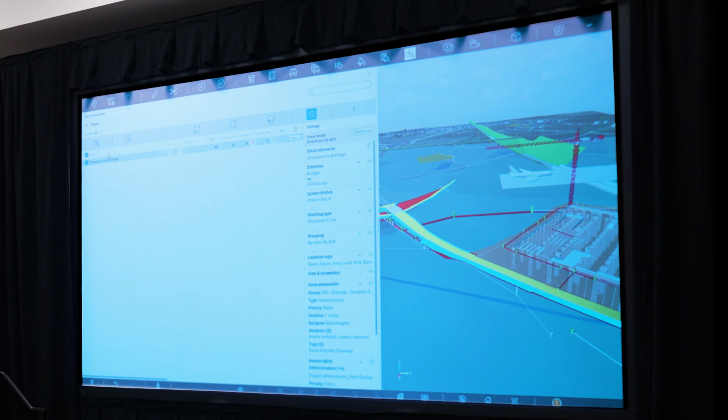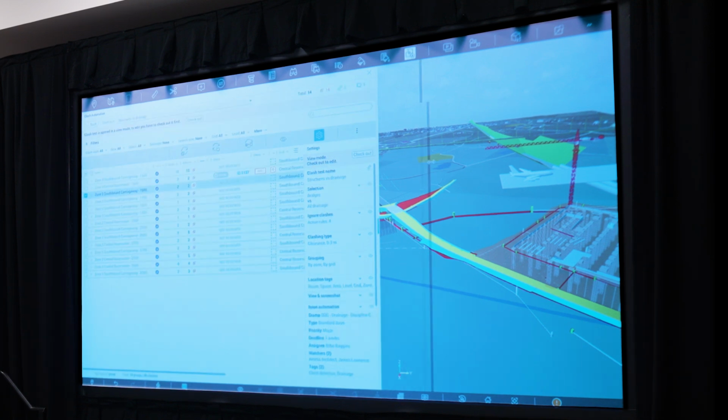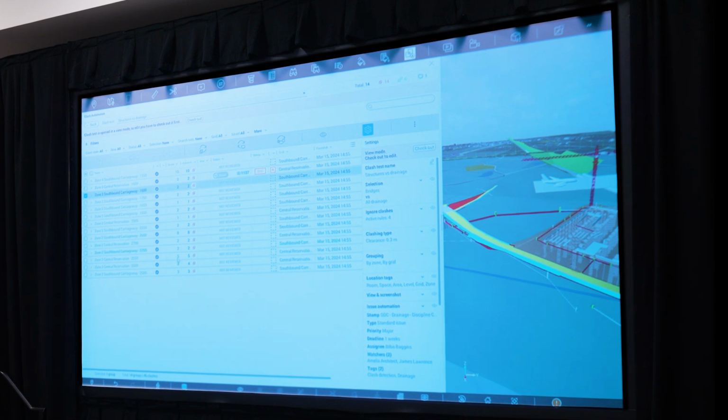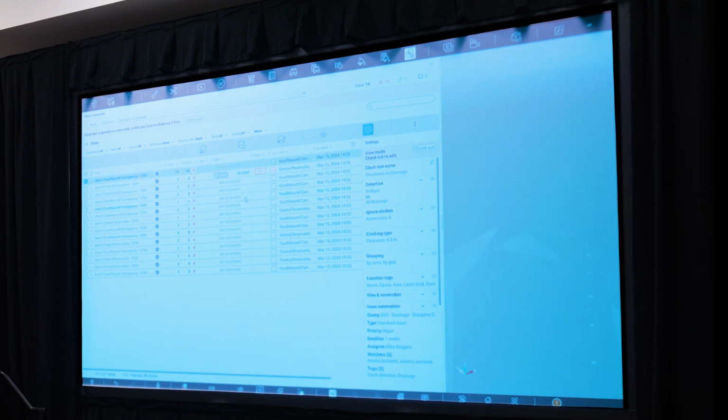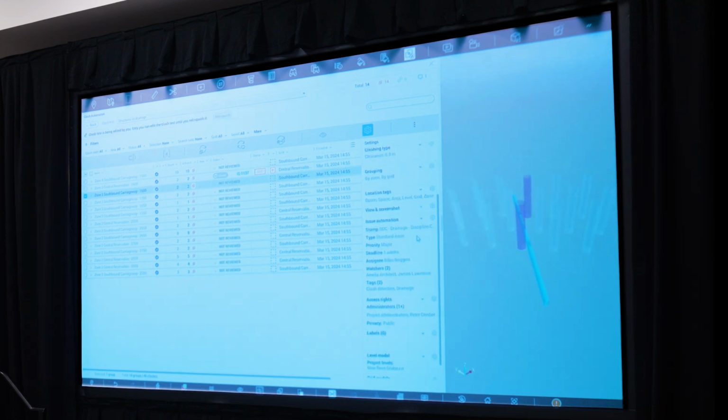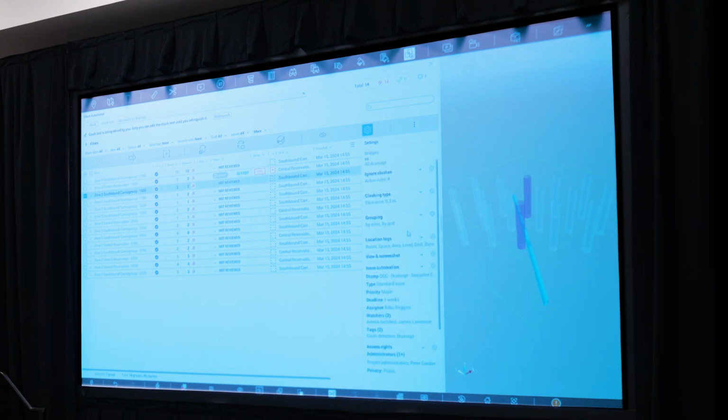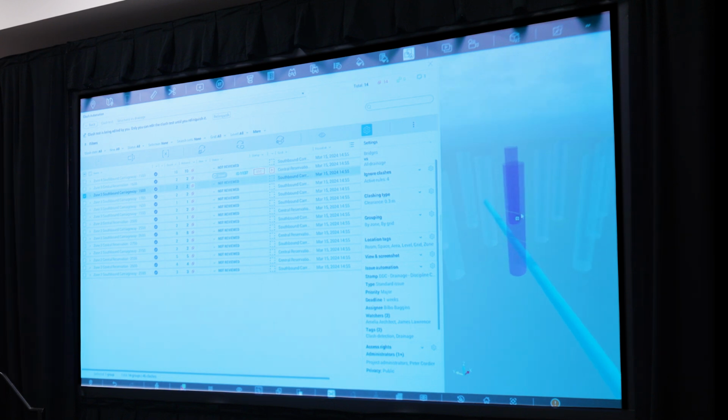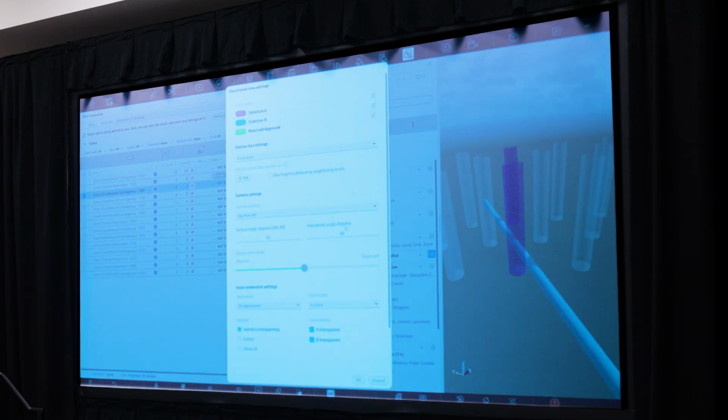So if I open this clash test, I've grouped the clash test results by zone, and then by the grid intersection. I've also changed some of the colours in there. I'm sure most of you, well, I don't know, who in this room knows much about the details of this stuff, but I like to change the clashing colours of my objects. Yeah, and you can do that in here.